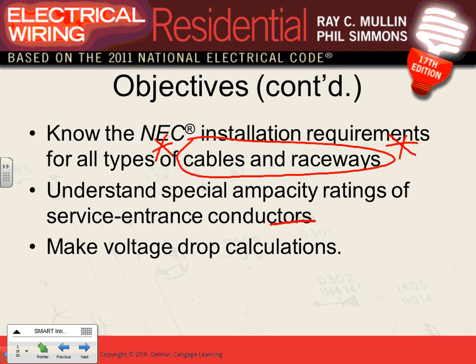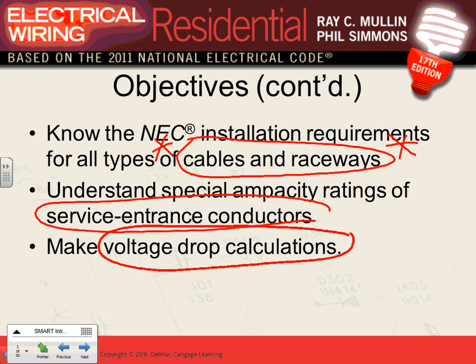Service entrance conductor, the use of service entrance conductor, we'll do that. Voltage drop calculation, guys, we'll do voltage drop calculation a lot when we do the commercial. So we'll do a voltage drop calculation. For the time being, I want to remind you, when we size a conductor, if you guys remember, based on three things. Number one, derating, if you need to derate. Number two, voltage drop. Number three, if it's continuous load. And we'll do a couple of examples on that one.